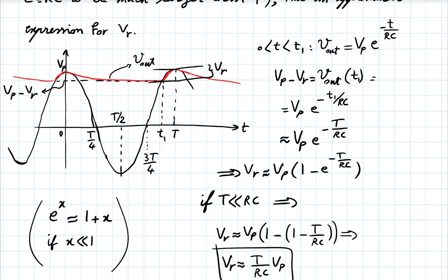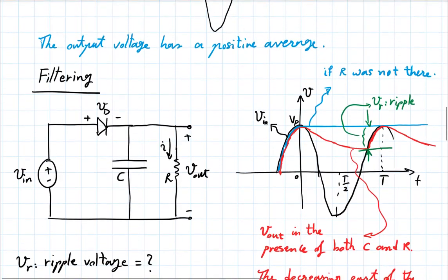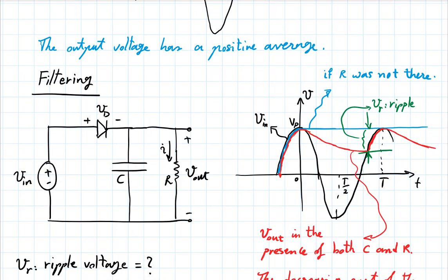Now, the resistor current throughout the cycle, again, thinking in the engineering approximation world, is basically the output voltage divided by R. And it's more or less constant, right? It has some ripple, but it's more or less constant with that average value that we talked about. So if you're interested in the diode current, you know that the resistor current is more or less constant. If you want to see when the diode current is very high, you have to see when the capacitor current is very high.